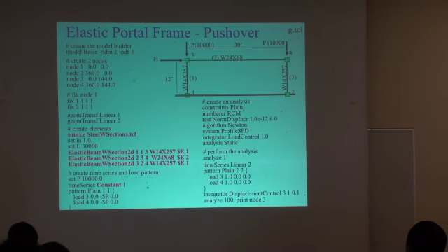Okay? What happens with OpenSees, you might come along and whatever the time is in the domain, this is our domain. The domain always keeps track of what the current time is. In a time analysis, that's what we think of as the time. And in a static analysis, it's kind of the lambda, or the pseudo time. But it's some value. We did load control 0.1, okay? And we need to analyze 10.